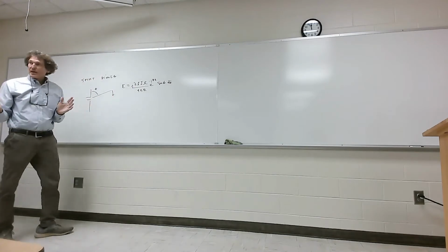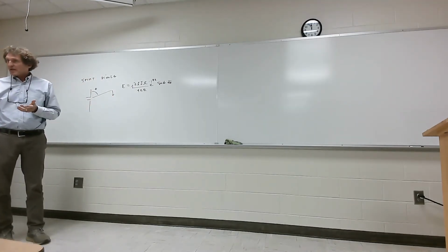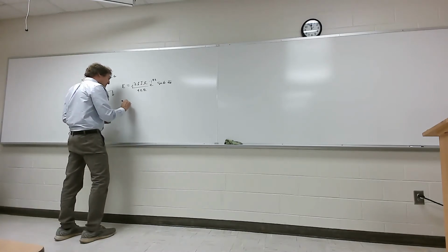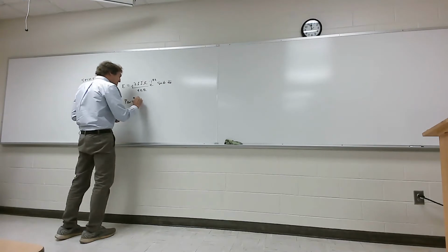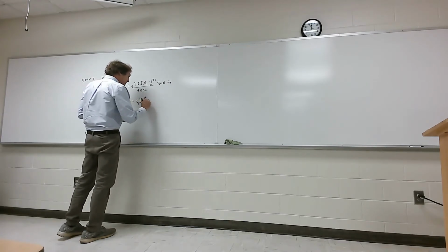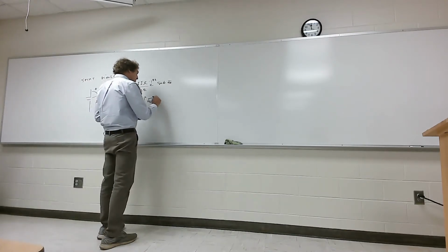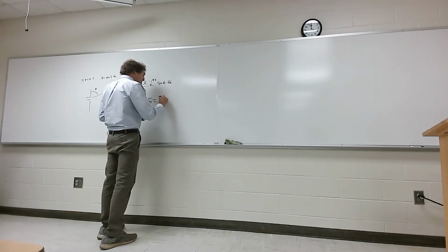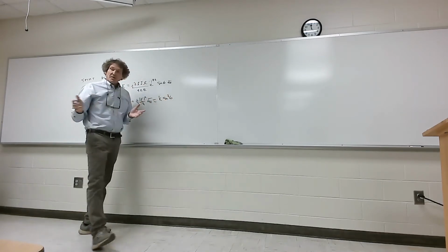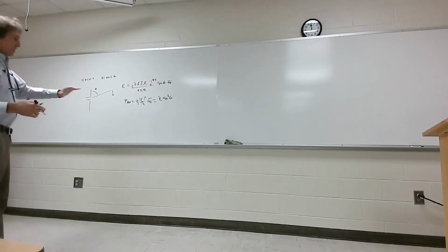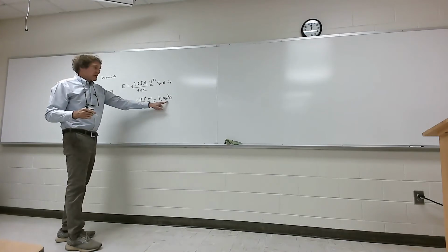You know this, right? If I go ahead and square this, I can say that the average power density is 1/2 magnitude of E squared over eta in the a r direction. You can get that too. You're going to find out it has to do with some constant right here times the sine squared of theta. Does everybody follow me on this? I'm not even going to bother figuring out that constant. It has to do with eta, beta, I, all that stuff. But it's a simple constant. It doesn't change. Y'all follow me? And yes, it is a function of r squared, but we don't care about that as much as we do how it varies with angle.